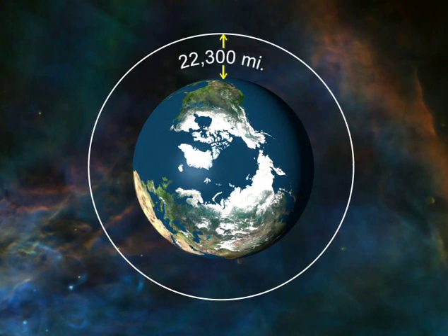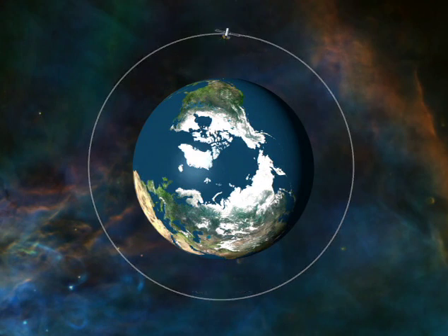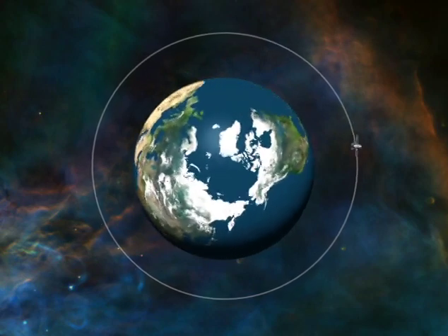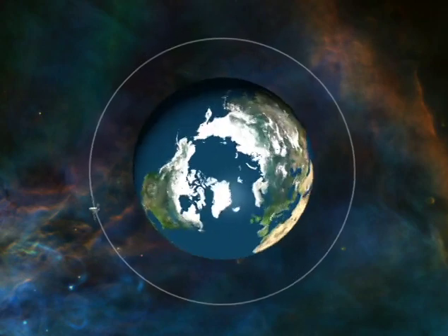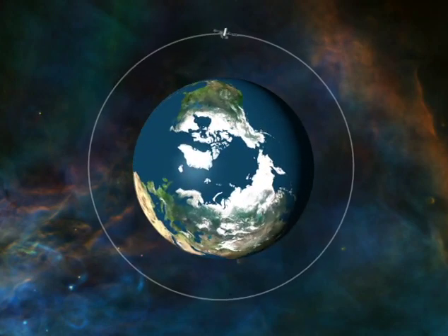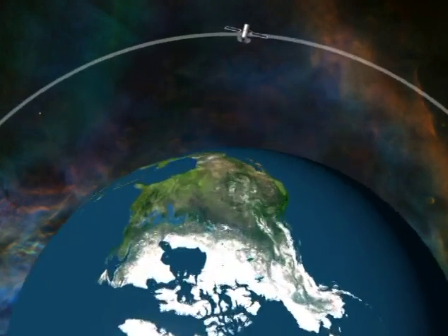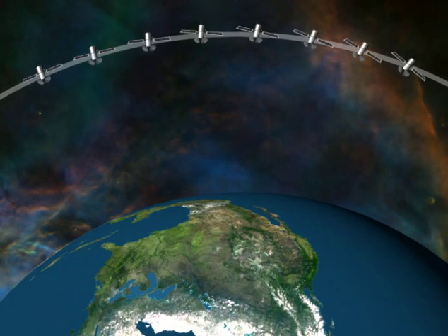The satellites are 22,300 miles from the Earth's surface in an orbit around the equator. This region is known as the Clarke Belt, after Arthur C. Clarke, who in 1945 worked out that an object at this distance in space would appear motionless from the Earth's surface. It moves around the Earth exactly in sync with the Earth's rotation, hence the term geostationary orbit. The U.S. has allocated 8 orbital positions, 9 degrees apart, roughly centered over North America, for high-powered direct broadcast service.